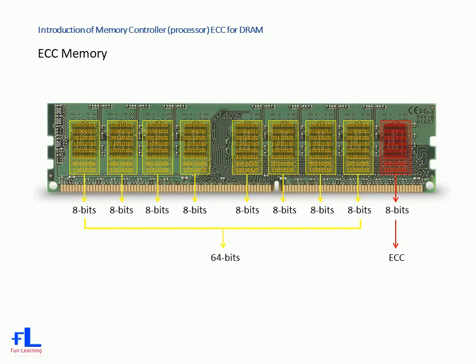Some computer systems build the ECC memory on the same PCB motherboard together with the processor. This is to shorten the memory data path, protect the data bus from signal noise, and avoid mechanical connectivity issues. However, it loses the memory upgradability.